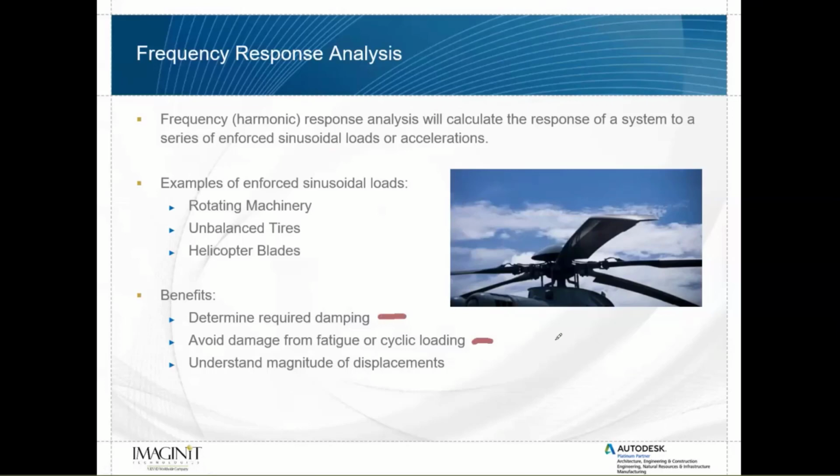Looking at this allows you to determine how much stress will be caused by this level of vibration, and over the long term, if this were to be a constant vibration, what level of fatigue we might see. And very importantly as well, we can understand the magnitude of displacement. So how much deformation will we see? Will we see the component or the assembly displace a significant amount to where we're having clearance issues, or will it be a manageable amount of bending or deflection?